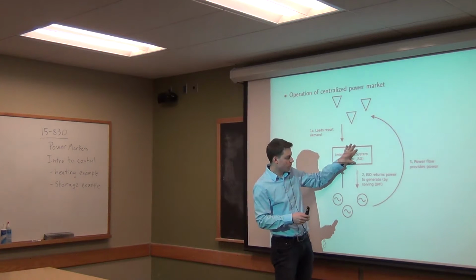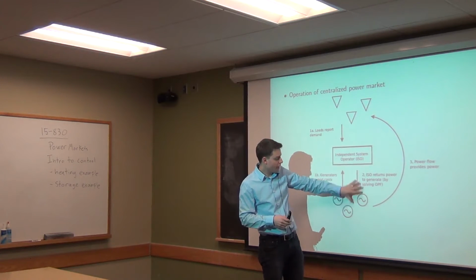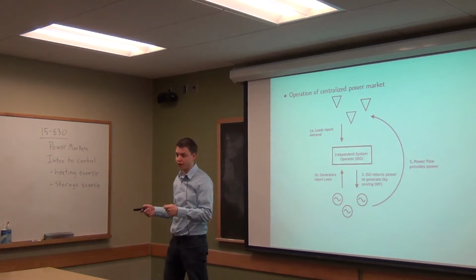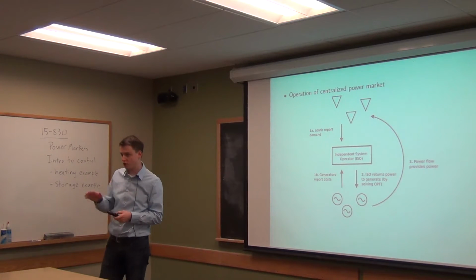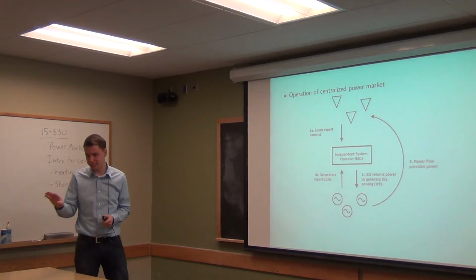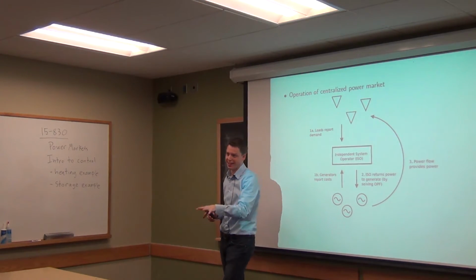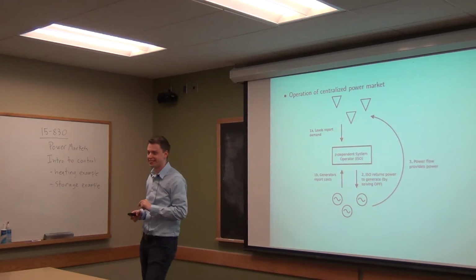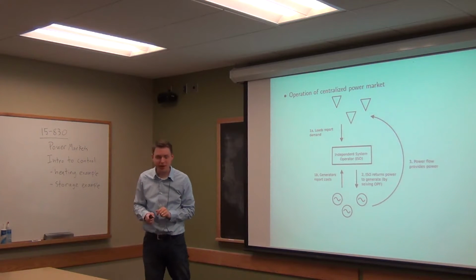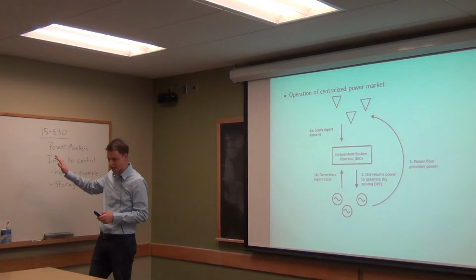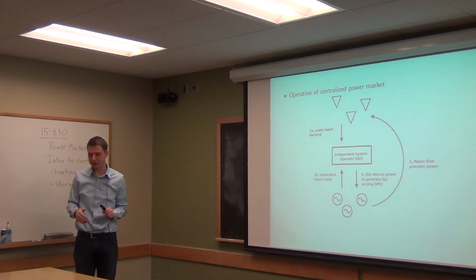So it solves that problem, gets those power generations, and then sends those back to all the generators and says, okay, here's how much you have to generate. And there are legal contracts that are binding in some respects where if you bid into the market here, you have to be able to generate that. So you cannot falter on your bid, or if you do, there's at least a big penalty. So you maybe buy it from some other secondary source, but you pay a big penalty in the meantime.